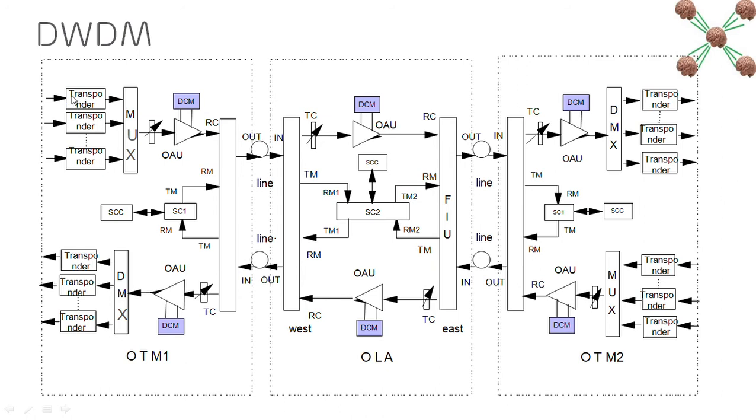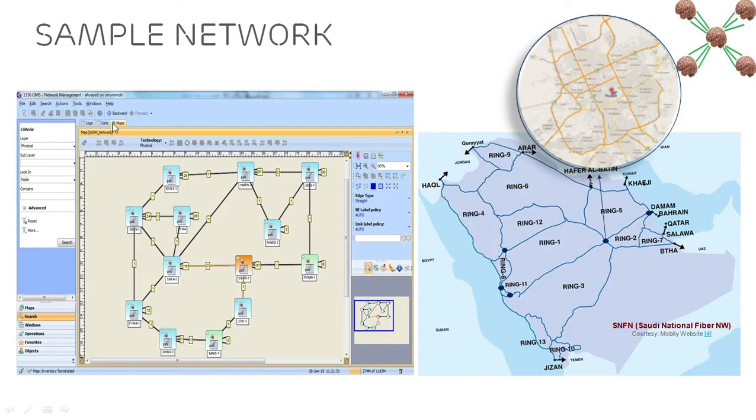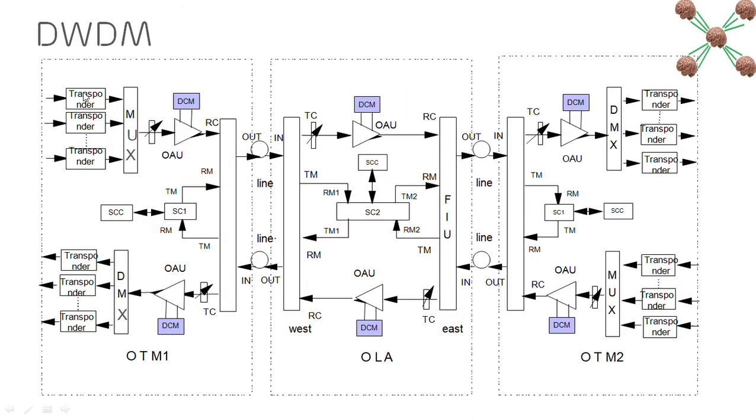This transponder should be based on the client requirement. For example, we can have a TDM transponder. We can mix it with an Ethernet transponder, and we can have, for example, a 10 gig transponder, and mix it with a 2.5 gig or a 40 gig transponder if the design allows. Sometimes it is not easy, but sometimes it is very easily possible to take different sizes of client signal on the same fiber. So you can mix and match as well.